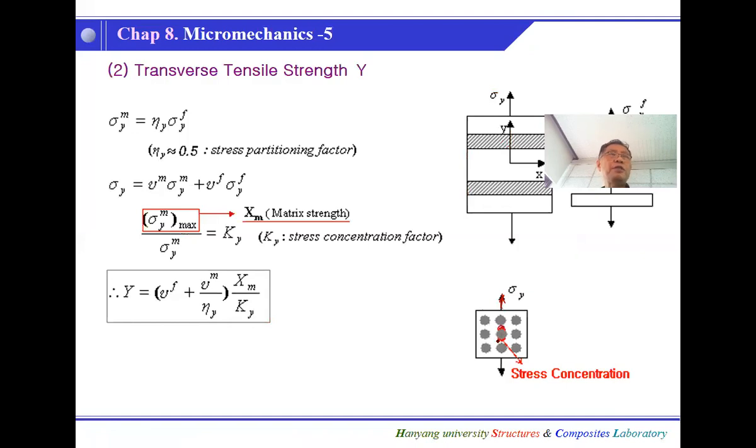The maximum point will depend on the fiber property, resin property, and fiber volume fraction. So each time we have to go back to a finite element program and get all the stress distribution. But once the failure occurs, the material property will degrade and the stress will redistribute. So it has a progressive behavior, which makes it very complicated.